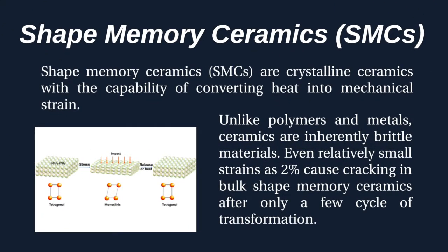So in ceramics, the ability to be shape memory ceramics is almost impossible, because ceramics have crystalline structures, and are inherently brittle materials. So even small strains like 2% can cause cracking. Only a few cycles of transformation can cause cracking.